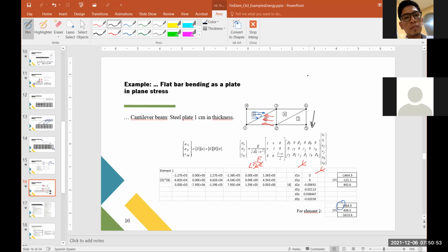I can say no, but the thing is that beam bending. Exactly. In the upper part, what do you expect in beam bending if you have a concentrated force on the right? And this is clamped. So you will have something like this. In the upper part will be tension. In the lower part, you will have compression. So it makes sense to have this negative and this positive. Now, you see that it's very strange, right? Because I have in this triangle, I have to the left, in the upper triangle to the right. Yeah, but this has more area. So I can think that it's like having a net force, in this area I have a net force to the right, and a net force to the left. And the combination of the two will give you the bending moment. So it makes sense. Okay.